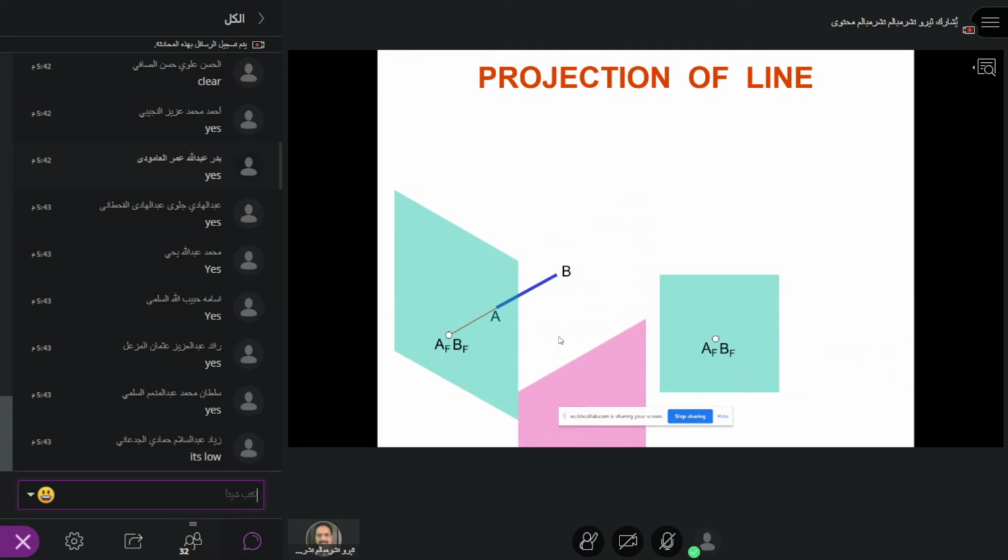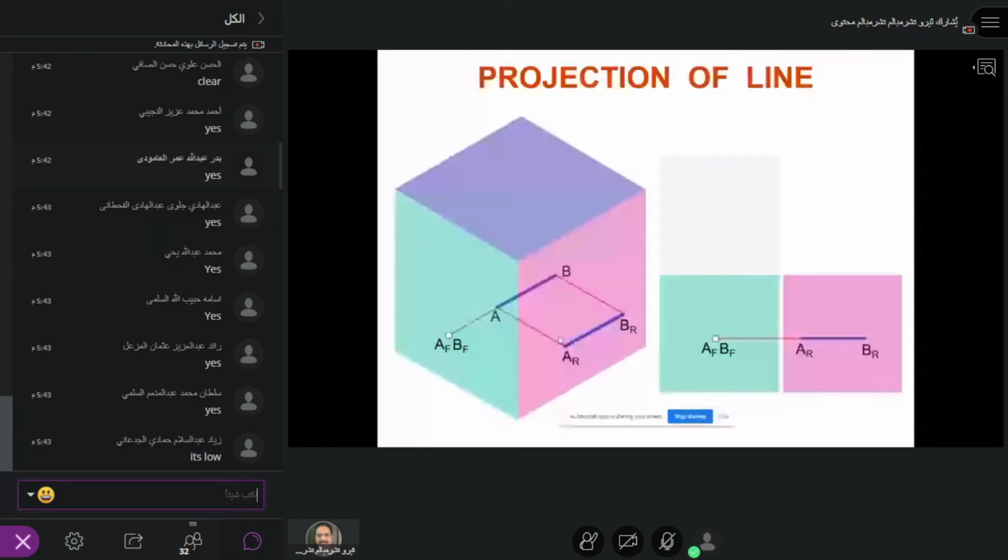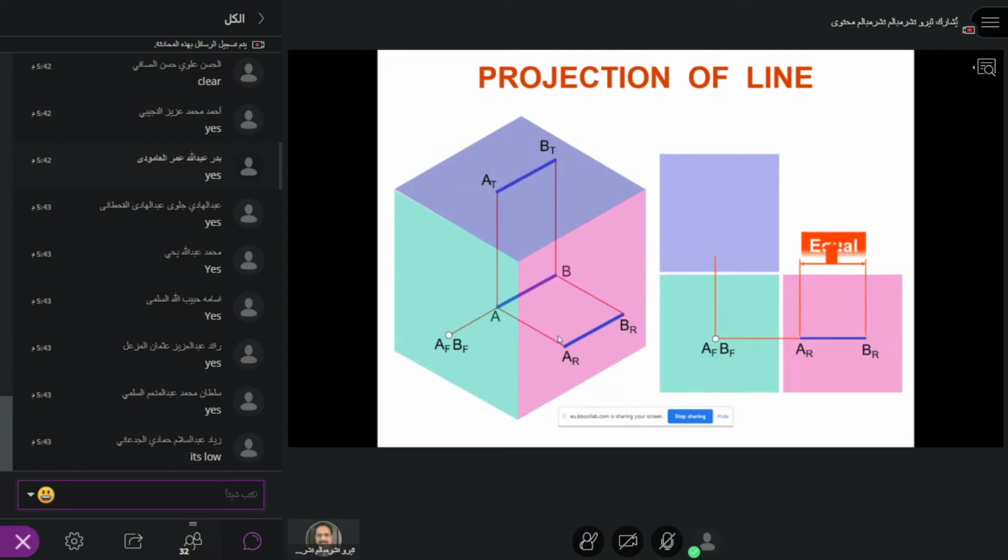Okay, I also use the top view here. I put the glass box on the top. I projected the AB. Now this is AT and BT on the top view. So now you see there, this must be of the equal length, AT, BT. So in order to visualize a particular object, I need to refer all these three views, the top view, front view, and side view, in order to visualize any component.